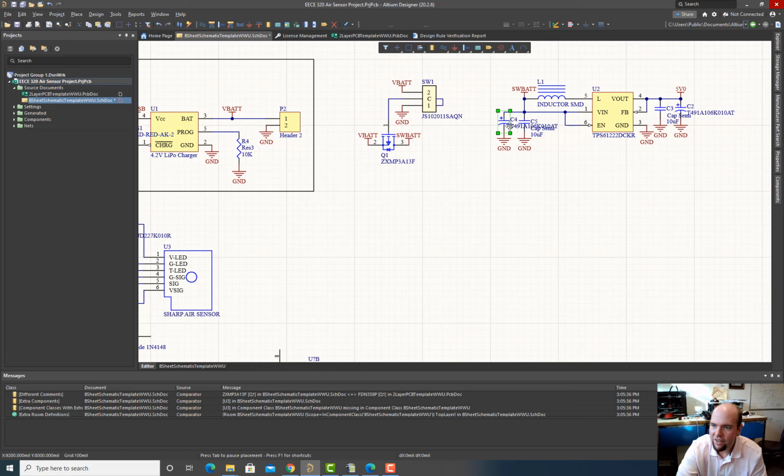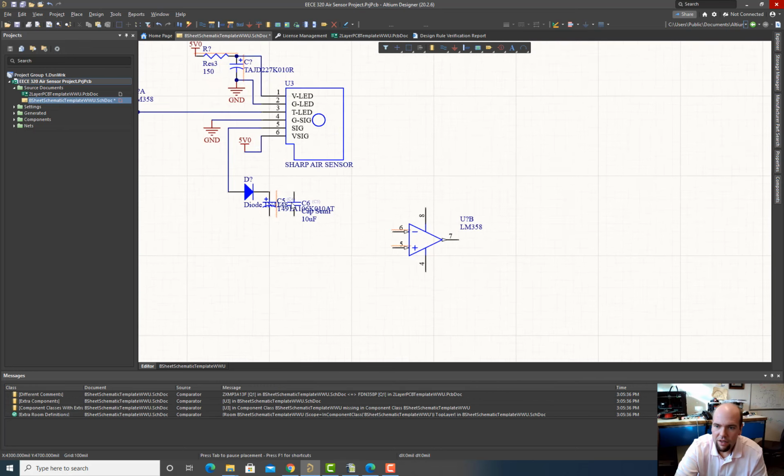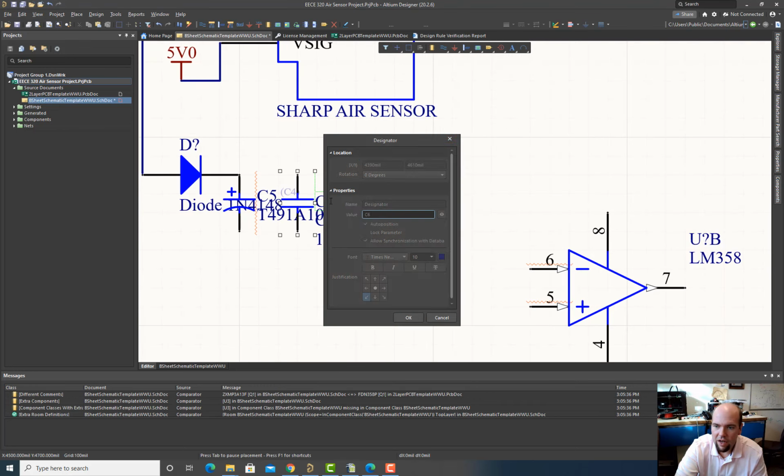See, now you see what it did when I shift grabbed this? Whoa. It created this C5, but C5 already exists, so that's going to be an issue, and I'll show you how to do that. If we put 2 capacitors in parallel, we don't have to populate them both. It just gives us options later on. I'm just going to manually do C question mark.